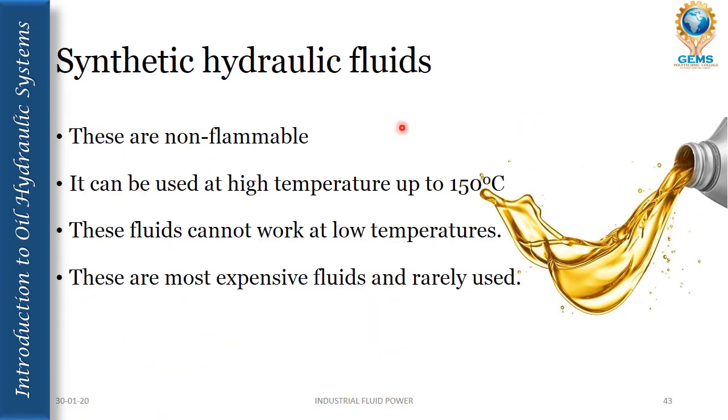Then comes the synthetic hydraulic fluids. These are non-flammable. They can be used at high temperatures up to 150 degrees Celsius. These fluids cannot work at low temperatures. These are the most expensive fluids and rarely used.